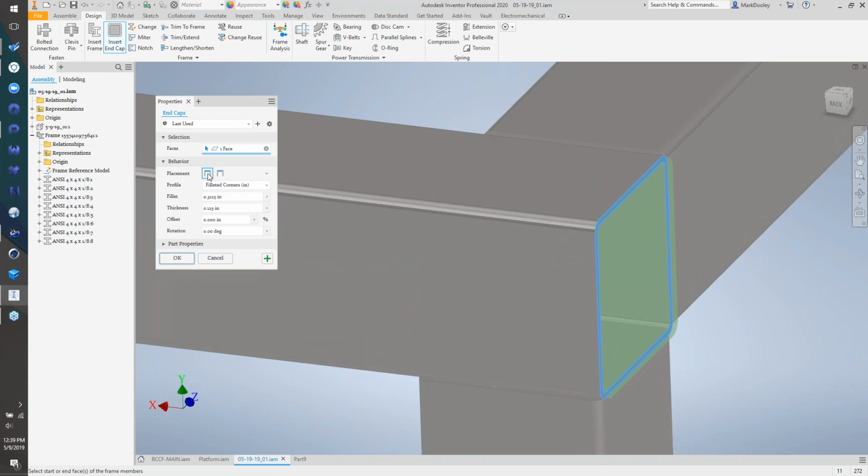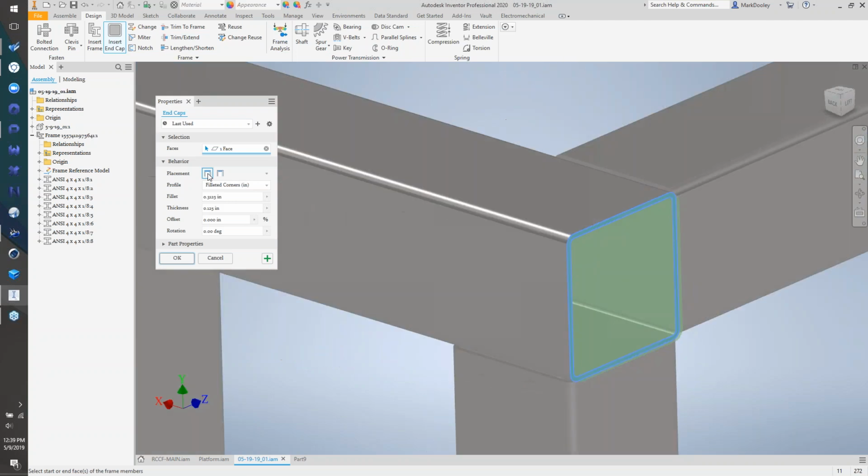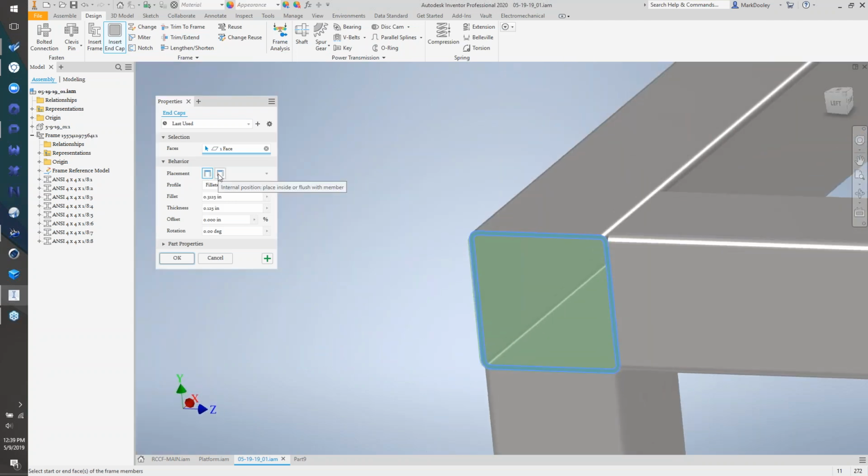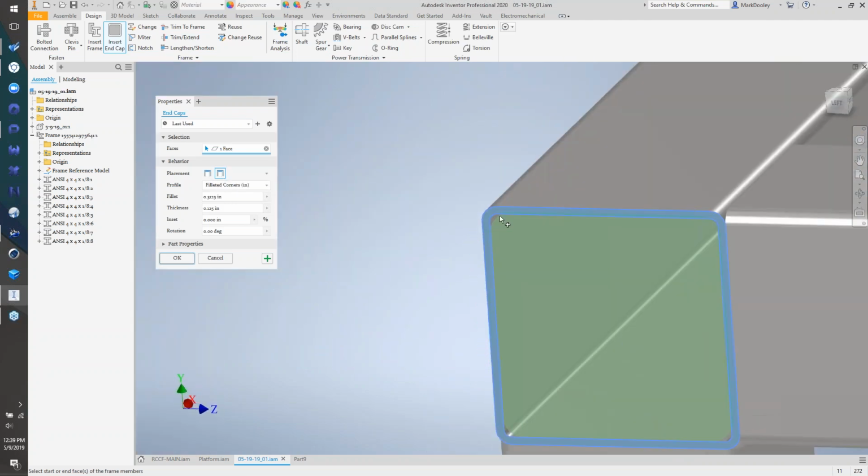Now you can publish your own shape. So this one might not be 100% accurate if I go on the inside where I get an overlap on the corners, but I can control the fillet right here. I can say, well, let's try this with a 0.5. All right, so that's a little bit more. That gives me more room to weld maybe. Or maybe if I want it to be a 0.25, it's going to be a little tighter fit. So I can control that as I'm putting this in here.